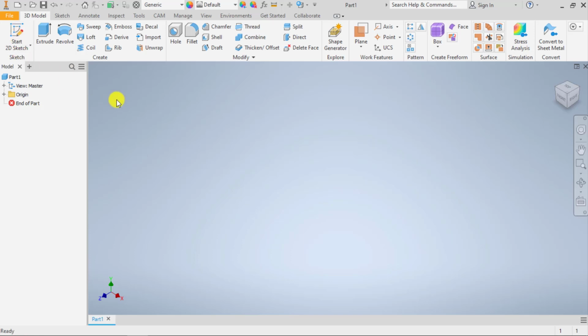So there are two main modes to Inventor. There's part mode or solid mode, which is what we're in now, and there is sketch mode. So the way that 3D modeling programs work, whether it's Inventor or Rhino or Creo or SolidWorks, is you sketch and you make a solid base off of that sketch. So sketch a rectangle and extrude it, you've got a solid looking extrusion.